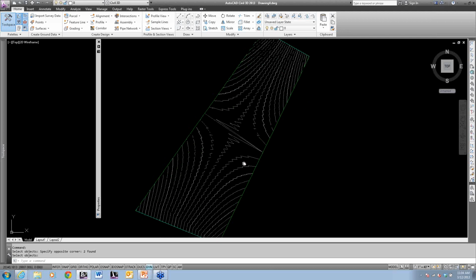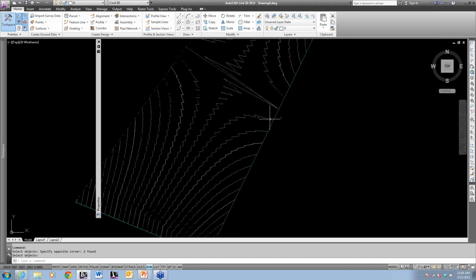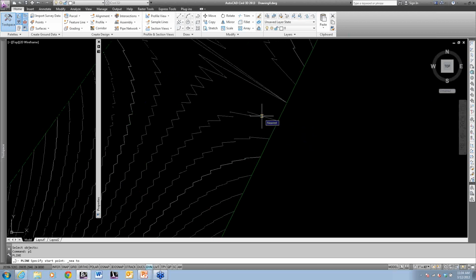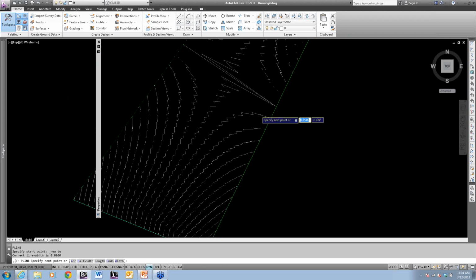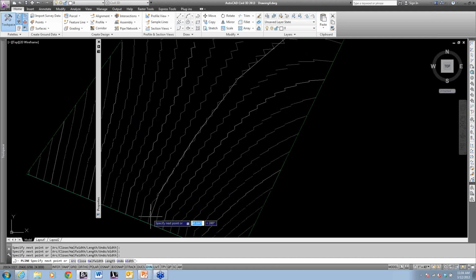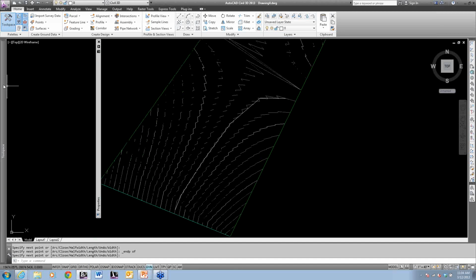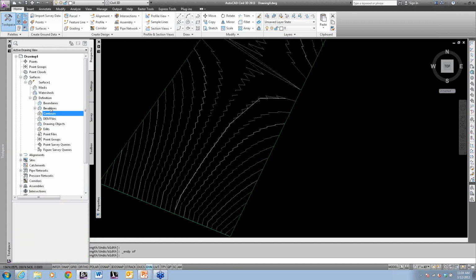Well, honestly, I draw contours a lot of times. So I want to smooth this contour out. What I'll end up doing is I'll just draw a polyline. I'll snap to the contour to start with, and I'll just say, you know what, I think this polyline should do something like this. I'll draw several of these, and then I'll end up adding that to my surface, either as a break line or a contour. It really doesn't matter in this case.